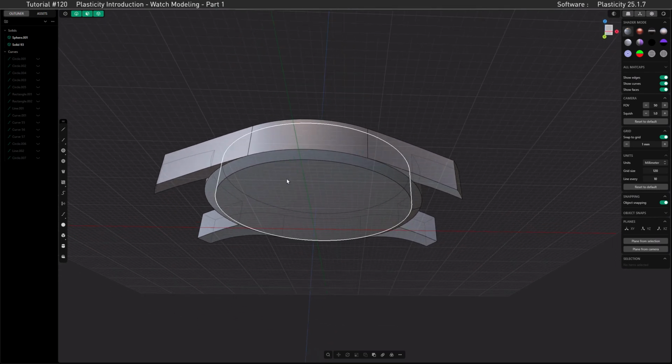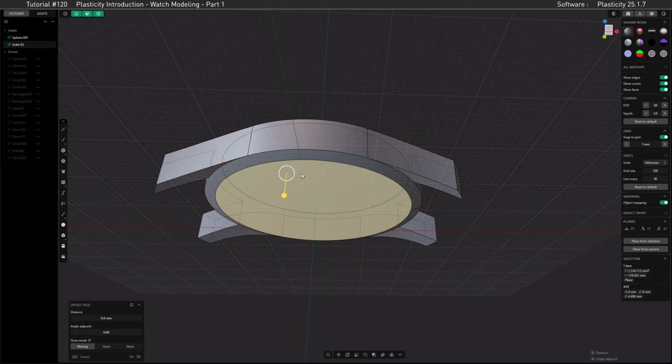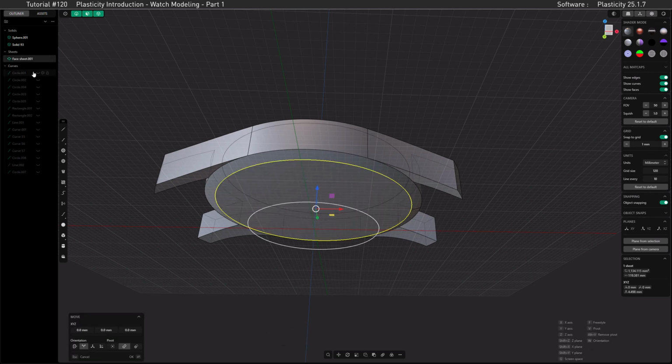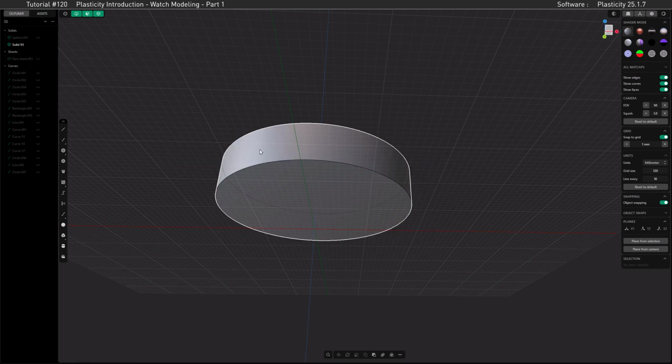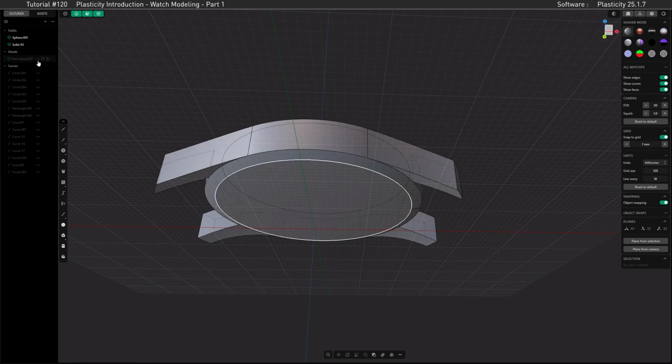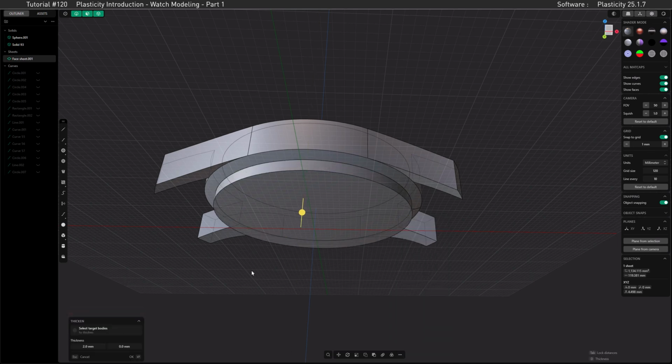have done here. As this is all part of the watch now, I want to create an extra piece for the backside. What we can do for this is select the back piece again. And while it's selected, we can actually duplicate that by Shift D to create another sheet. So since this has been duplicated, the original watch face here is untouched. And since this is a new sheet, we can use a new command on it, which is thicken. And we want to thicken it by 2 mm. and enter to confirm. Here we go.